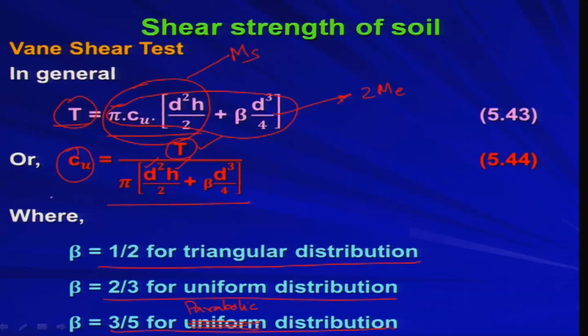Those are purely based on laboratory experiments, right. However, you can get the shear strength parameter from the field itself. Sometimes people find out the Cu value from the laboratory as well as from the field and then match them. If you get quite a significant difference, then of course there should be some kind of problem. If you get quite matching magnitudes between these two values, one from in situ and one from the laboratory, then of course your determination of shear strength is okay. This is the way people do the validation or comparison in the field.